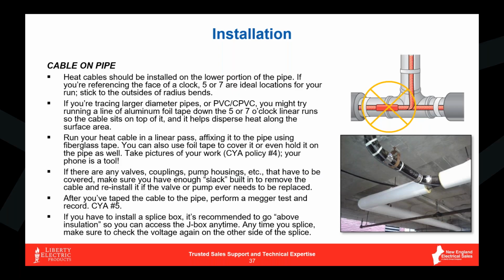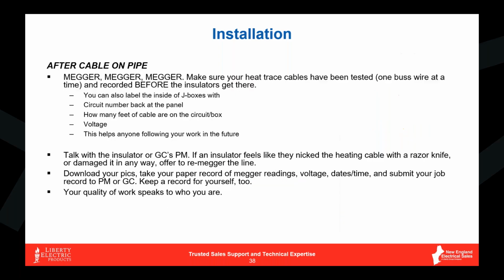But again, take pictures, show those terminations, because the other thing that happens is, if there's an issue down the road and it's a question of product quality, or hey, this is defective, whatever the case may be, the factory is going to look for immediate proof. Okay, so that is why it is critical to keep a record of your installations. When we do this, you could forward all of that information, and generally figuring out problems is a lot like a process of elimination. So the more you can do to help yourself on the installation with that CYA policy, the better off you're going to be in the long run.